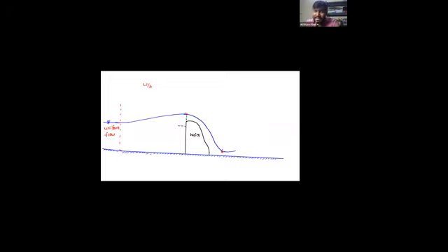But once it hits the ground level, do you think the energy is conserved? No. Once the water hits the ground, the energy will be dissipated, yes or no? And now, as the water is rising against the gravity, what is open channel flow? Is open channel flow a gravitational flow or against the gravity? Gravitational flow. Once the water rises against the gravity, it rises up and falls down. Rises up and falls down. And this is known as a hydraulic jump.